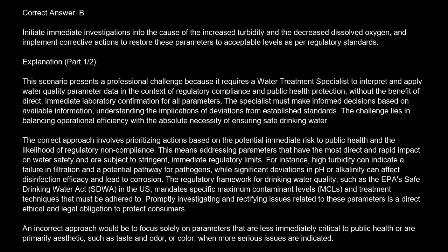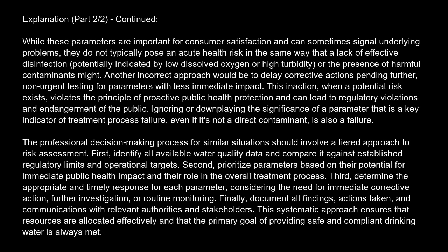An incorrect approach would be to focus solely on parameters that are less immediately critical to public health or are primarily aesthetic, such as taste and odor or color, when more serious issues are indicated. These parameters are important for consumer satisfaction and can sometimes signal underlying problems. They do not typically pose an acute health risk in the same way that a lack of effective disinfection, potentially indicated by low dissolved oxygen or high turbidity, or the presence of harmful contaminants might.